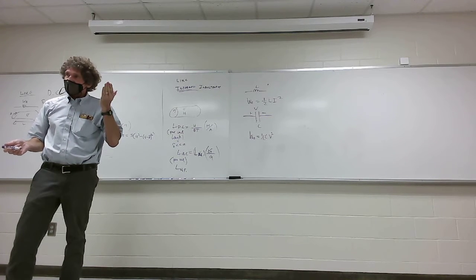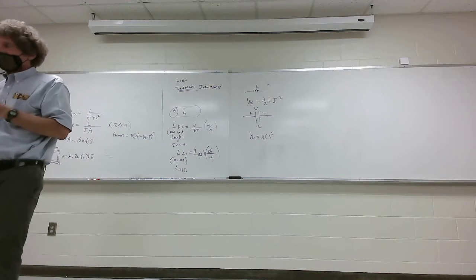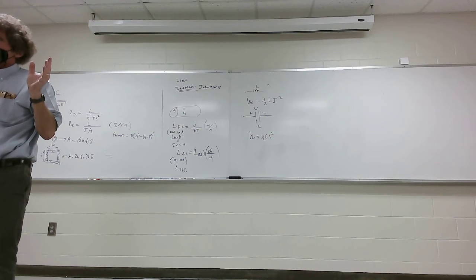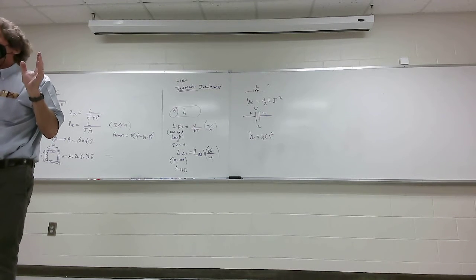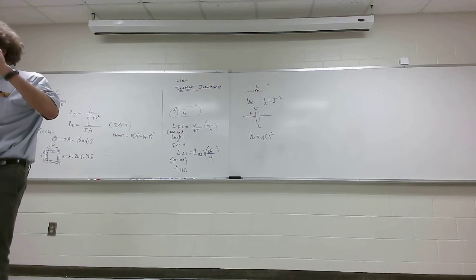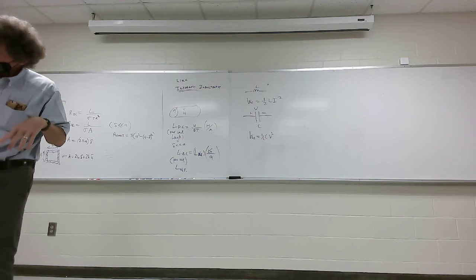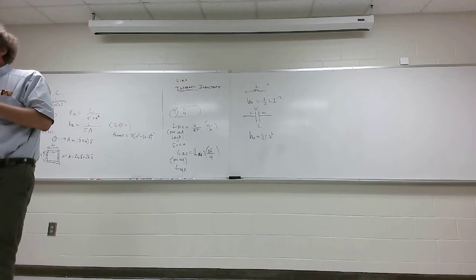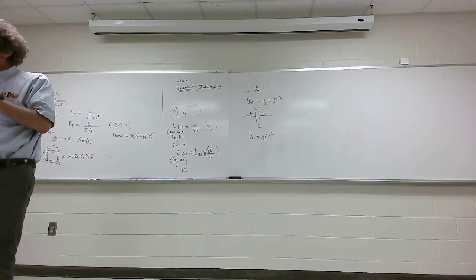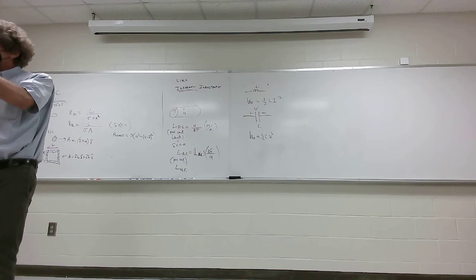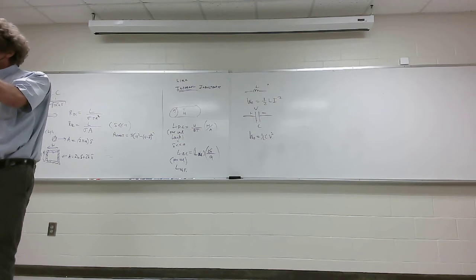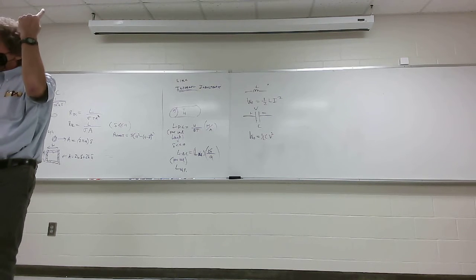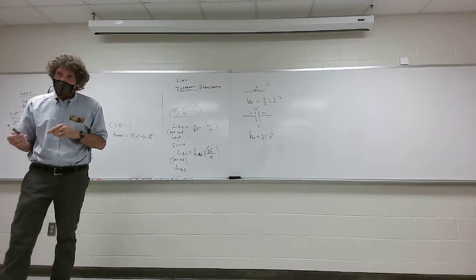Do y'all follow me? I learned a hard lesson in this with railguns one time. It had to do with cabling hanging all over the place when we did discharges, up to 400 kiloamps, by the way. I learned there was a ton of energy in the air, for starters, to cause electrical shocks. I literally saw arcs out of that wall down to the ground happening because of this. And I'm not going to get into all the physics that are happening. The other thing is, if you have current and there's a magnetic field, there's I dL cross B as a force, right? Well, boy, was there a force. The thing was like a whip, all right? We found that out the hard way. It didn't dawn on us how much force would be generated.